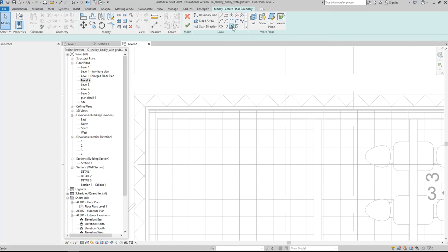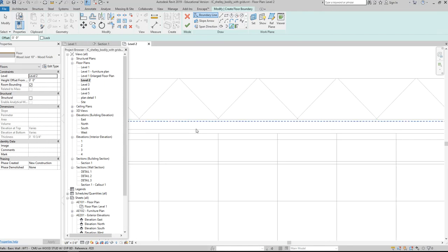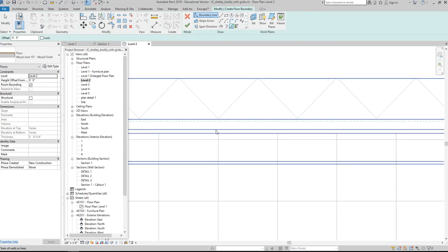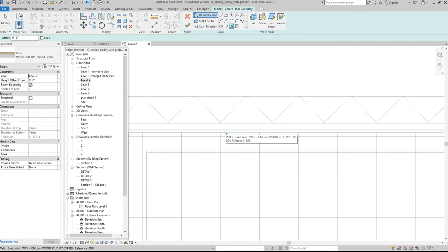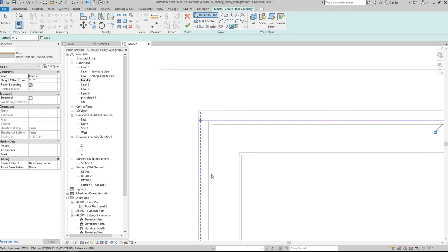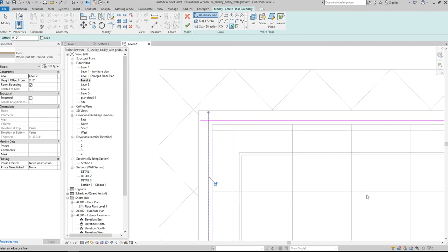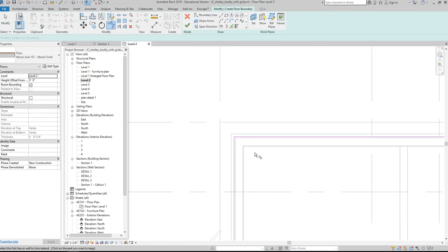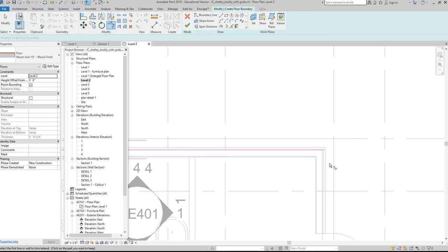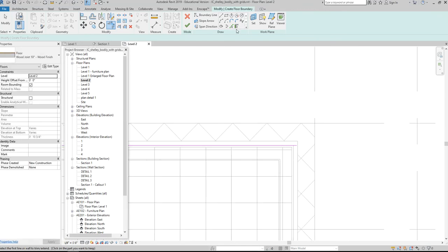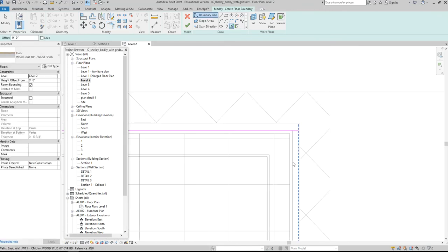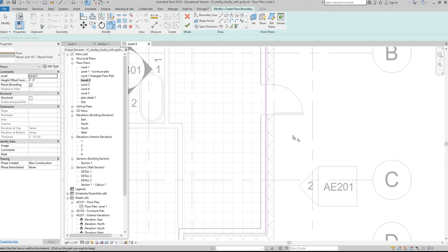So I'm going to click on my little pick tool. I'm going to come over here, I'm going to tab till I find the line I want, and I'm going to click, and it created my line. Tab, click, and it crosses over, so I do have to trim that up a little bit, but the pick tool is actually really easy to use, right? So we'll just continue on with that. Tab, click, trim, and you'll get really fast at this, right?